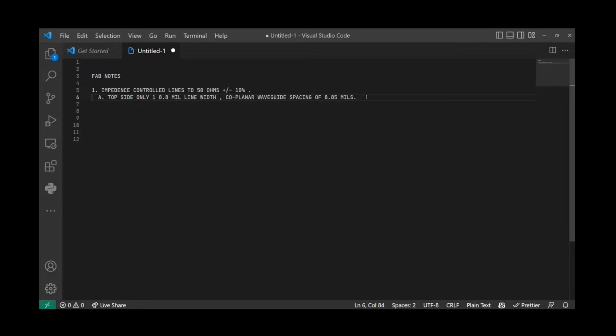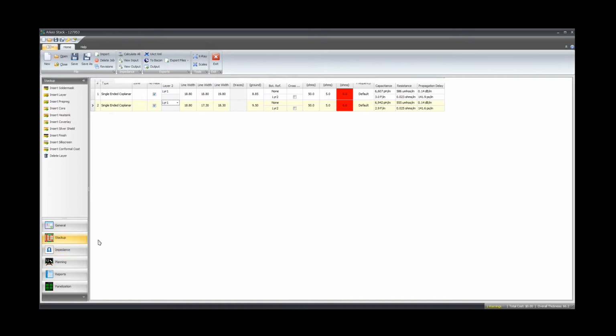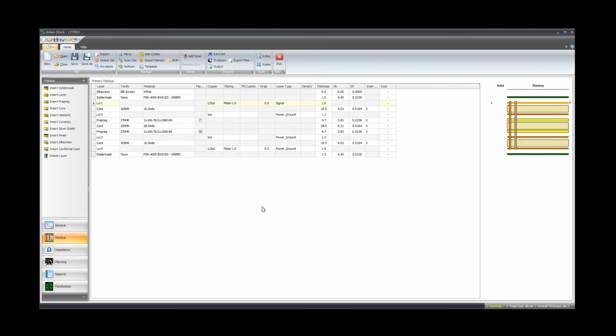With some of those requirements, you build a model for your PCB stack up. In the manufacturing process, we use software tools to build models that tell us exactly what the PCB stack up is going to look like, what materials are going to be used, and exactly what impedance constraints we have in the stack up. So, for example, the impedance design we looked at is a single layer impedance on layer one, our top layer. We've got, for example, half ounce copper on that layer. That's going to be a factor in the impedance constraint.